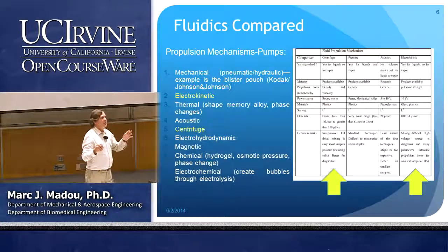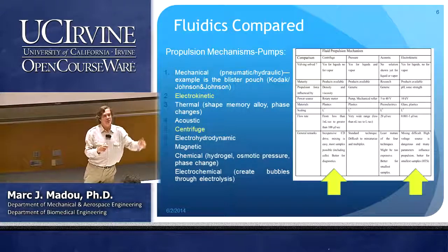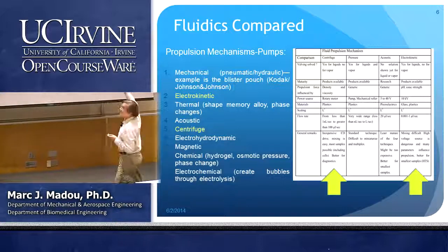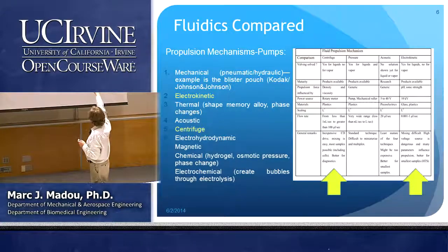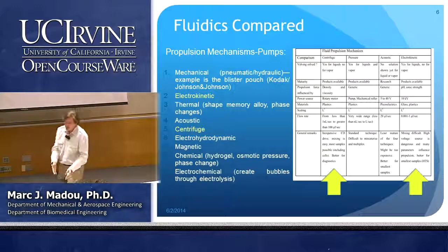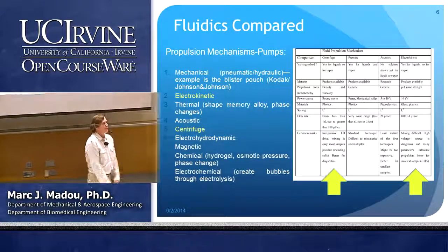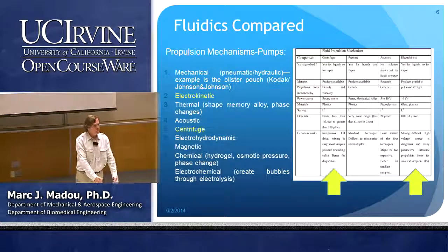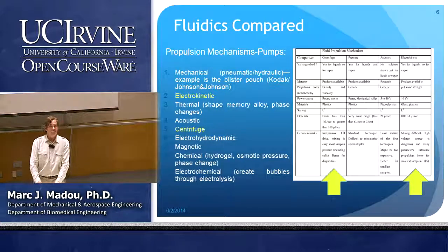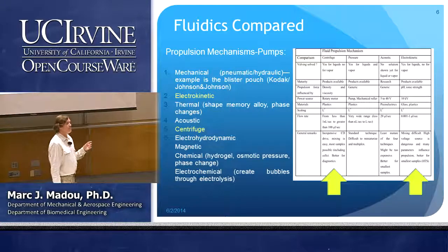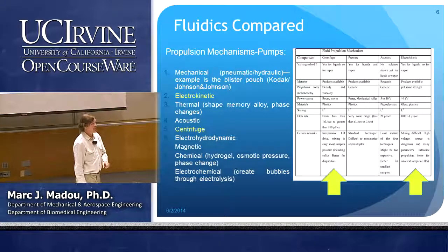But not pH, not ionic strength, things that will influence the electrokinetic method. In the electrokinetic method, when pH and ionic strength are different, the pumping strength is different. That's not very convenient, is it? Because almost any liquid that you use will have a different pH and a different ionic strength, and the pumping force will be different. In other words, electrokinetic pumping depends on the sample nature.